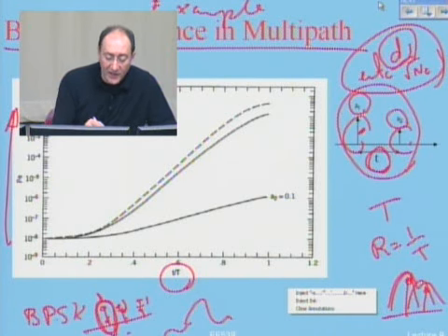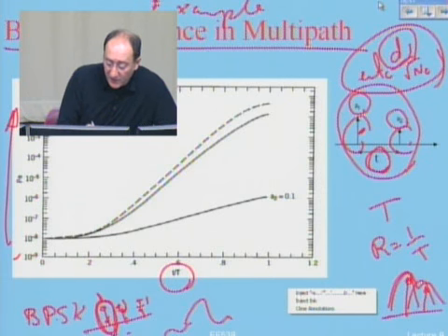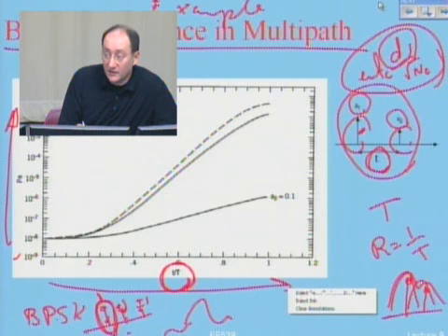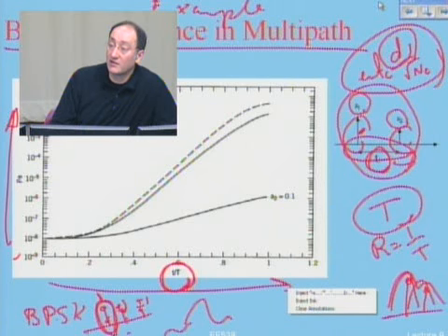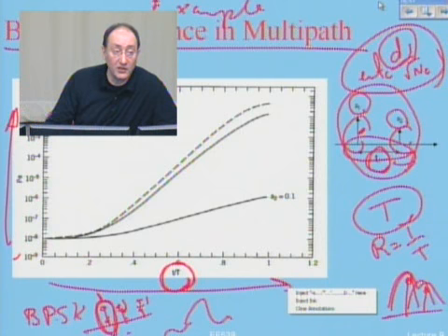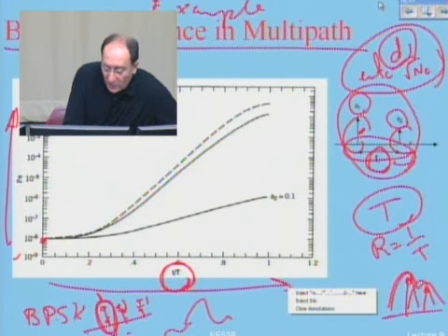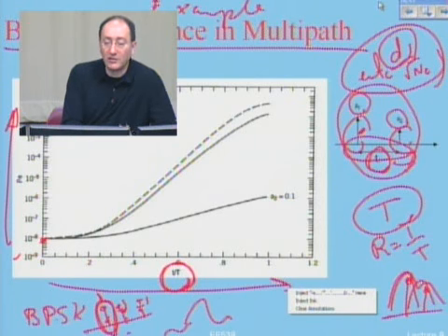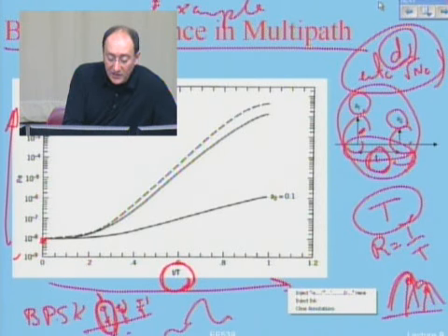And if you calculate that probability of error versus T over capital T, which means the multipath spread over the duration of the pulse or transmission period, I get something like this. At the beginning here, when it's 0, the two paths are on top of one another and my error rate is 10 to the minus 8.